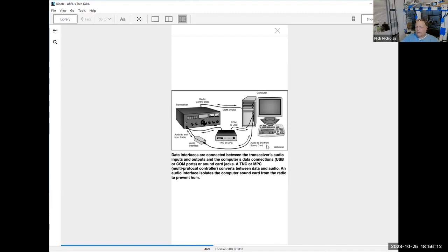So to connect FT8, you read the manual with it, it'll tell you, it's pretty simple to follow, but you do need audio out and microphone in for the FT8 signal to be able to operate. And you connect your adapter to this. By the way, this shows a setup which really isn't common, but it does exist.